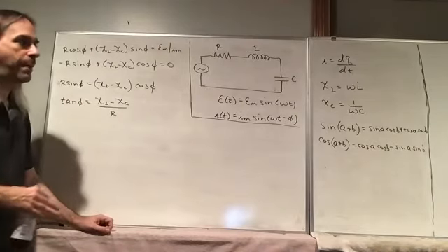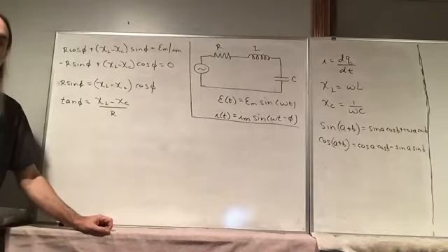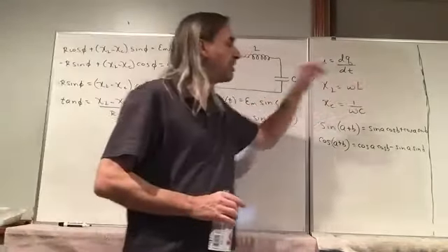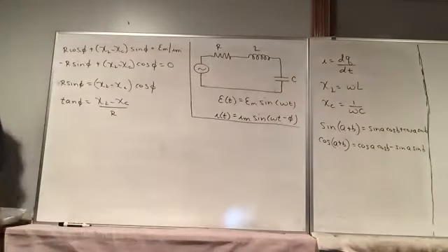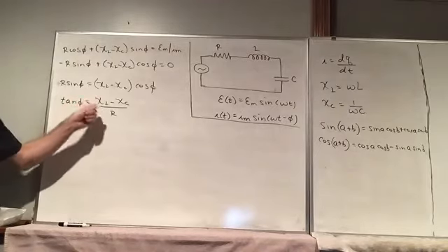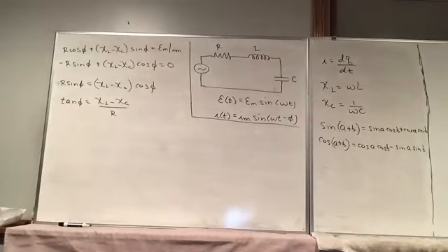These both have units of ohms. We can show that, like this is a Henry per second. Using our unit conversion factors, we can say that's an ohm. The other one is a second over a farad, same thing. You can just multiply by the right conversion factors and see that those both have units of ohms, just like the denominator.